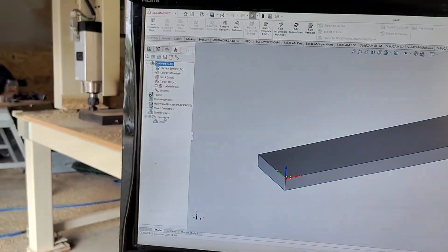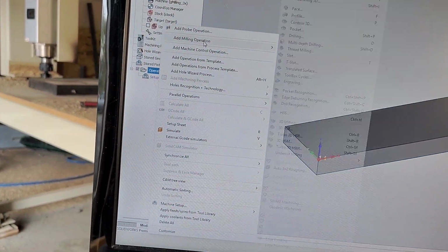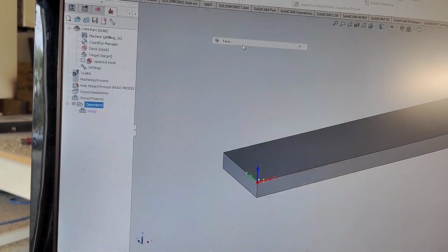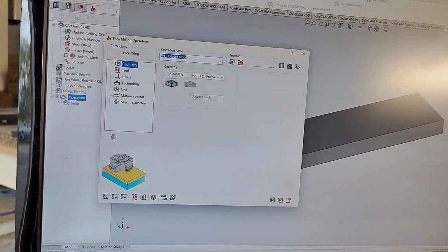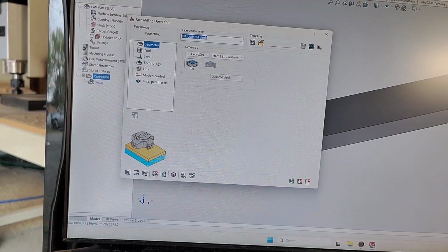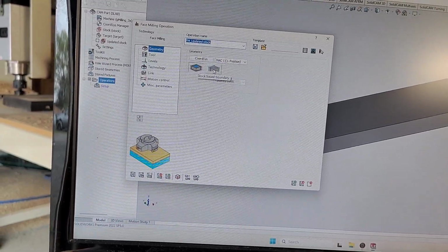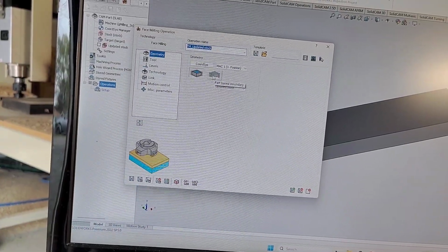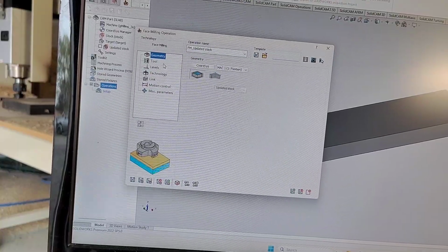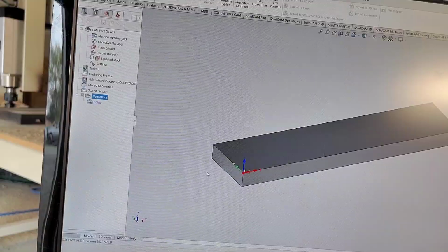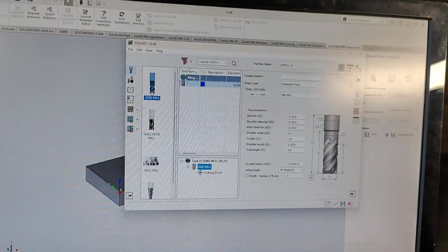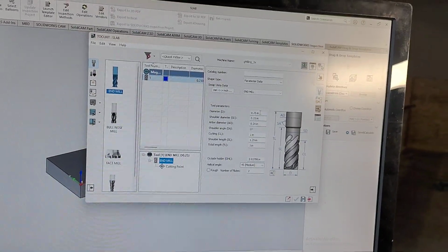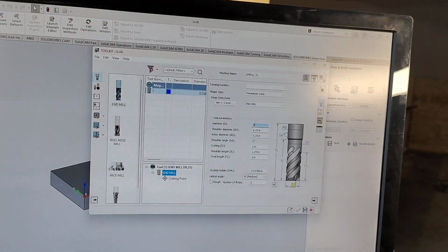And so you just right click on operations and add a milling operation, and then for slabbing the face, we'll go to face. And the geometry on a face operation is basically based on the stock, or you can select part of a drawn stock, but we want the whole thing. So we'll select this guy, choose our tool. It's end mill. And these tools, you can save them for future use, so you don't have to do this every time, but our diameter is 2 inches.